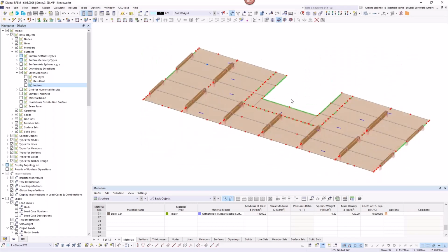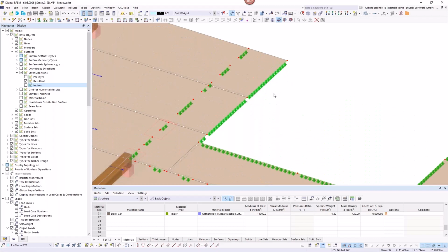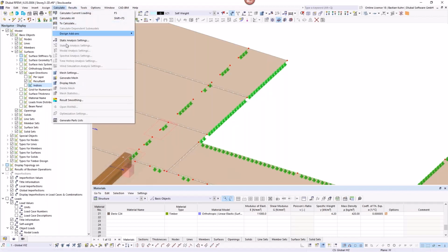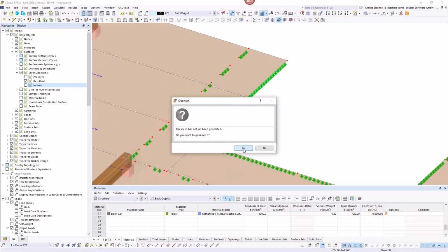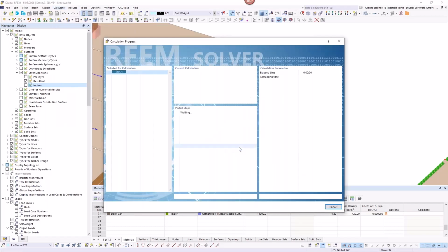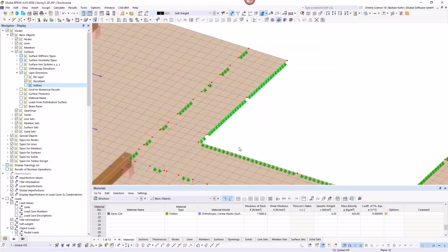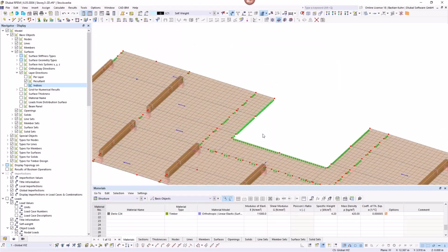All right, that is the plates. I also defined supports, just simplified, also only vertical and not movable in X and Y direction, because as we are only looking for vertical forces and deformation, I think this is okay. I will generate the mesh just to show you another part, what I made in this model.